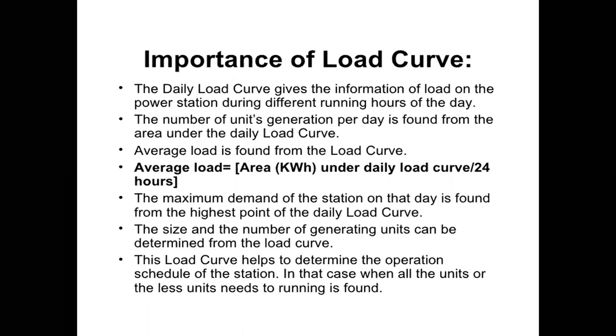Maximum demand on the station on that day is found from the highest point on the daily load curve. The size and the number of generating stations can be determined by the load curve, and this load curve helps us to determine the operation schedule of the station, that is, when all the units or fewer units need to be running. So these are certain importances of the daily load curve.